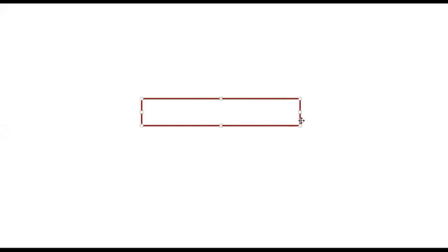So first we need to understand what pure bending is. A beam is said to be in pure bending when, for example, if you have a beam like this, it may be a simply supported beam or an overhanging beam. Let us consider a beam. If it is subjected to a moment, or you can call it a couple, like this, then its shear force diagram will look like this.